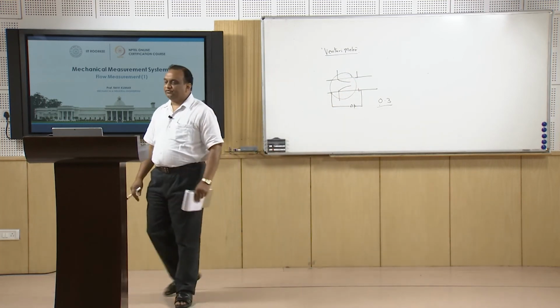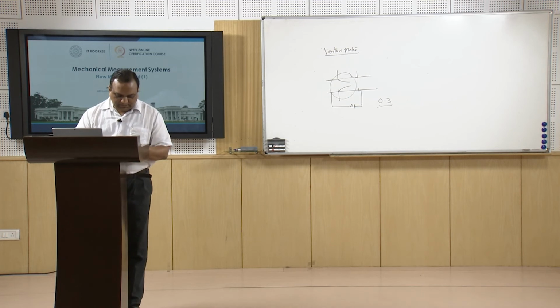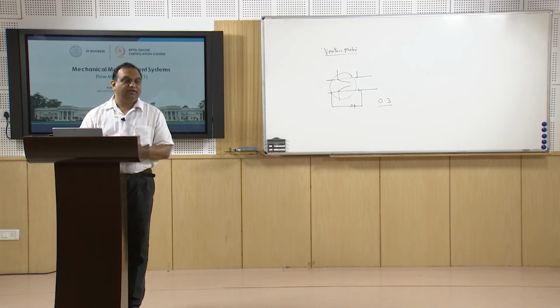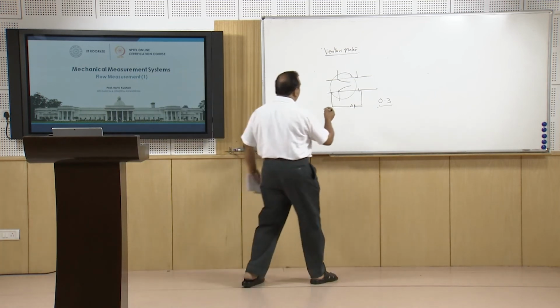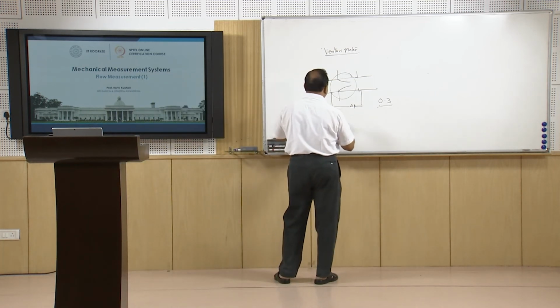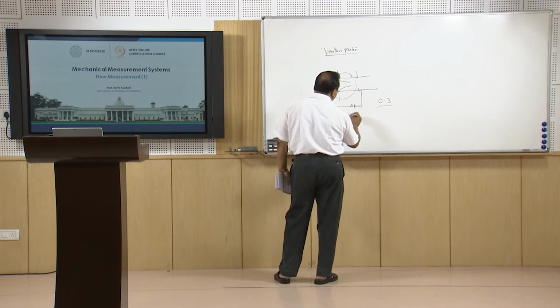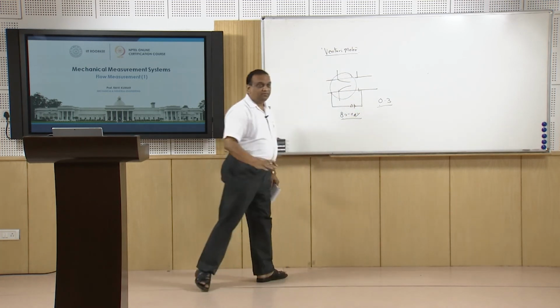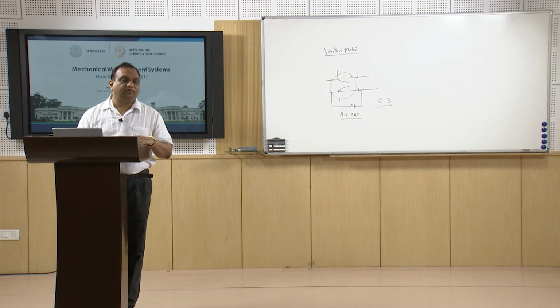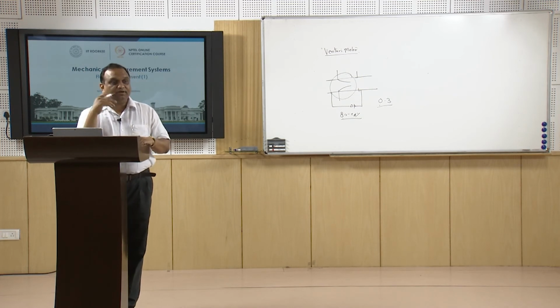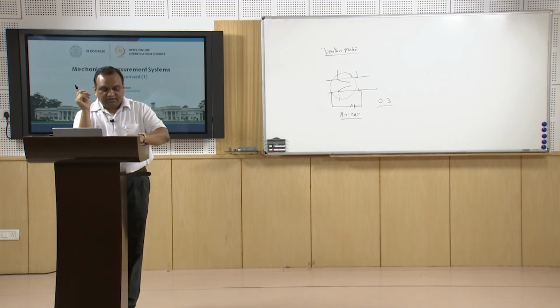Because when we talk about gas flow, in that case, the change in the density of the fluid has to be taken into account. And in this sonic flow, pressure recovery is approximately 80 to 90% of the differential pressure. So, pressure recovery is not very high, not very good in the sonic nozzle, but it is better than the orifice meter, or it is between the orifice meter and the venturimeter. It is cheaper than the venturimeter, right.